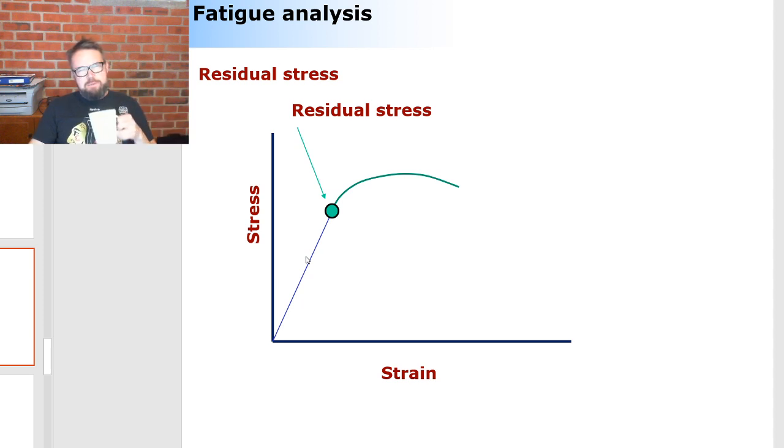This representation is typical behavior for steel material. Once you're loading your structure, the strains will increase, and the stresses as well. Once you reach this point, everything is still fine, and once you release your load, the structure returns to the origin of this curve. When you increase the force from the linear range to the nonlinear range, this is where plastic deformation comes into play. Now if you go all the way here and release your load, you're not going back to the original undeformed configuration,